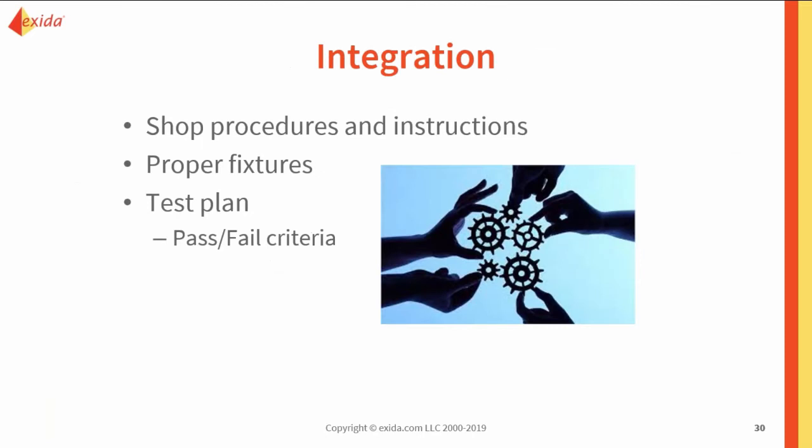Another portion of the design review that you need to do for integration is the integration itself. When your people are putting it together, are there procedures? Are there fixtures? Are there instructions? Does everybody know what they're doing? Or is it just bolting something together and putting it out there? Are you testing it? When you are testing it, are there instructions for testing? Are there pass-fail criteria? If something fails, do your guys on the shop floor know what to do? Do they send it back and have it reworked, or is it just kind of left there?